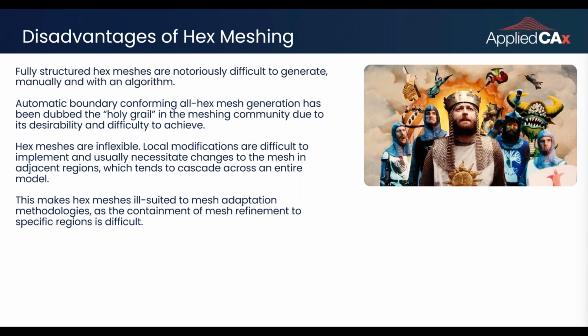With implicit analyses, if your results are more accurate, you'll be able to take bigger steps through time. Your convergence will be faster. And so there's another situation in which if you want to spend the upfront time creating a high quality hex mesh, you'll probably see the dividends in run times with that implicit analysis as well. So those are two major reasons for using the hex mesh.